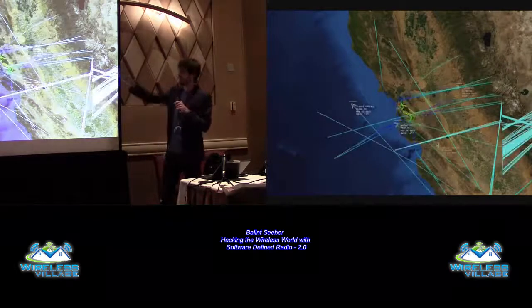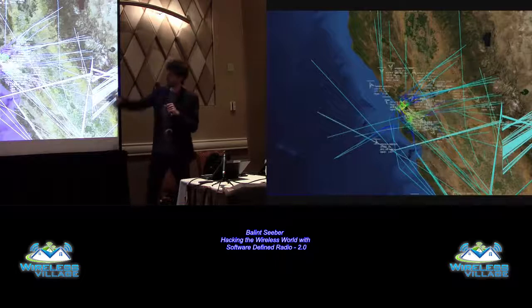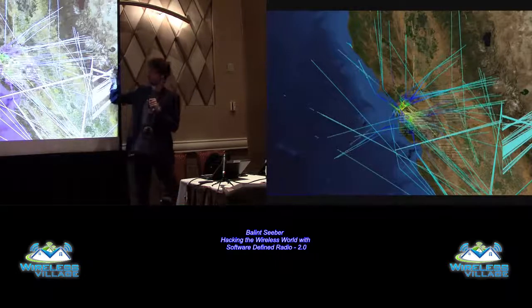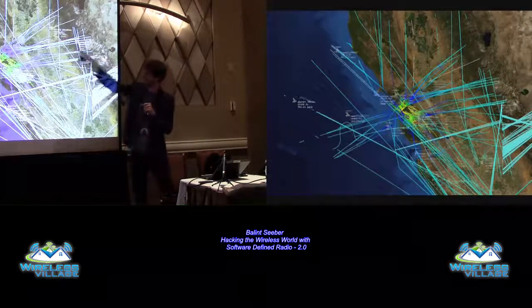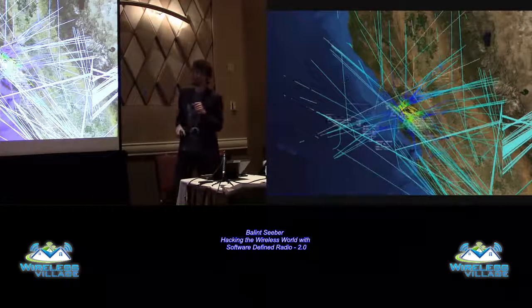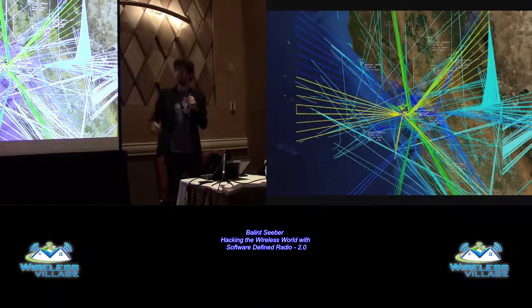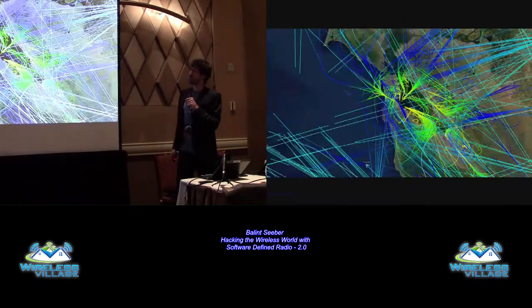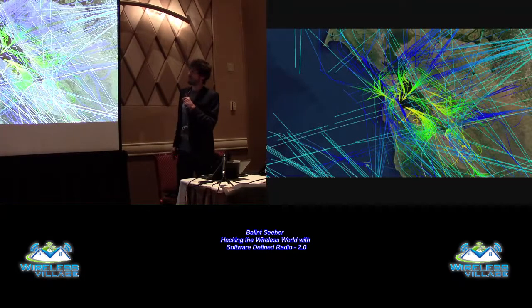So this is a system I put together called Aviation Mapper. These are all the planes flying through the Bay Area. You've got SFO, SJC, and Oakland International Airport. When transponders go bad, they produce all these crazy graphics on your screen. Basically, the position reports are flipped the wrong way around, so you get what I call these sort of colored rainbows. You can produce really nice flight trails to see where the air traffic is going.